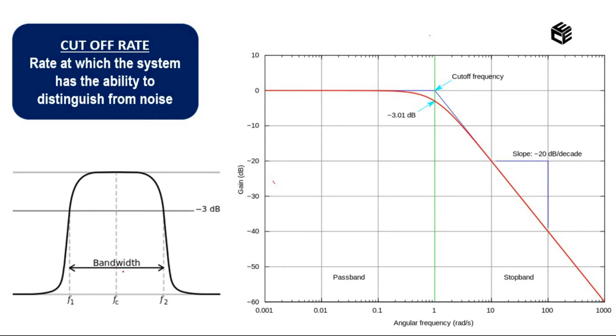On seeing this diagram, you can say what a bandwidth is. I have drawn a response. From this response, I have taken a 3 dB bandwidth from the resonant peak. This is our resonant peak value, and this is our resonant frequency. Correct.